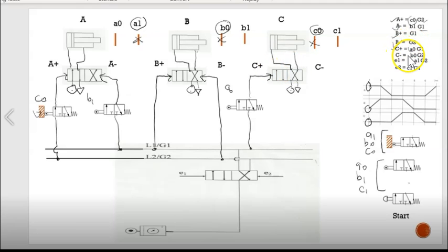Okay, look at C minus. C minus is B0 G2. So B0 is this kind of limit switch, the contact one. So put it here. Label it as B0. And we know that if the contact here, we're going to use this side. So it will connect from C minus here to G2. So G2 is here. Okay, don't forget to do the loop this time. So we connect this side to G2. Okay, do the loop here. And then we're done.